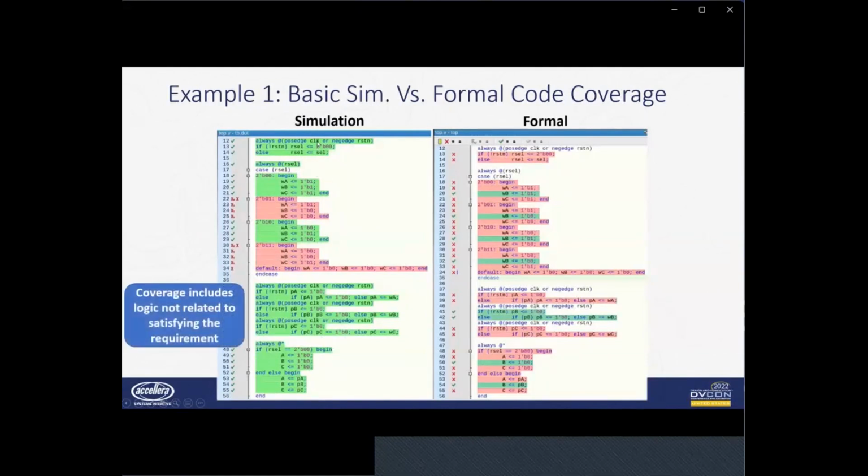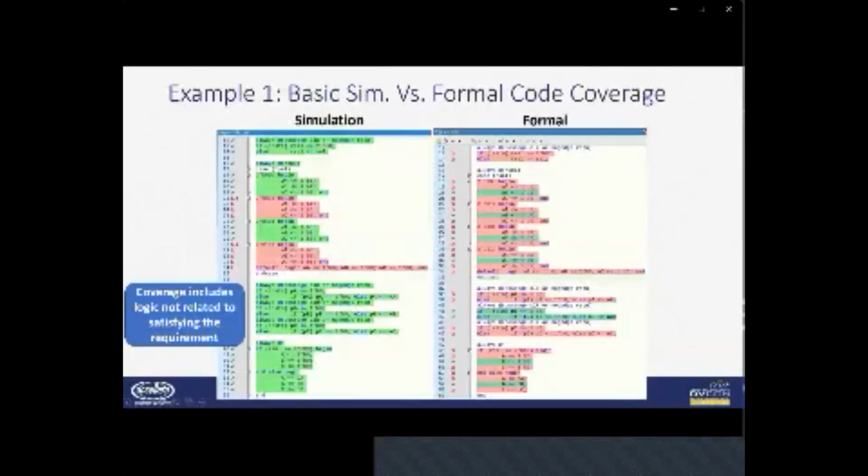And as you look at this, you'll see that the vectors start coming in on the inputs and will traverse through the logic, and anything it touches is going to be covered. It's somewhat of a forward traversal. The property we ran in simulation here, of course, passed. And the select inputs, we did not use the values of 1 or 3. We were only stimulating what would drive the output B in this case. But you can see a lot of stuff was covered that we weren't intending to hit. Anytime you go into a block, of course, you're going to cover every statement in there.